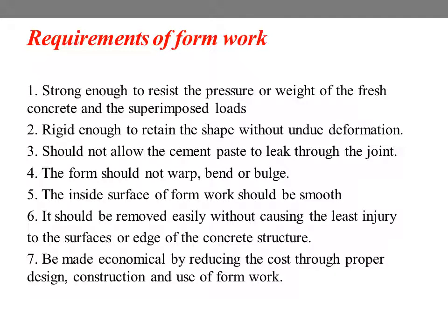Regarding requirements of formwork, it should be strong enough to resist the pressure or weight of the fresh concrete and also the superimposed loads due to the equipment, men, etc., if any. It should be rigid enough to retain the shape without undue deformation. It should not allow the cement paste to leak through the joint. It should not warp, bend or bulge. The inside surface of formwork should be smooth so as to give good appearance to the resulting concrete structure.